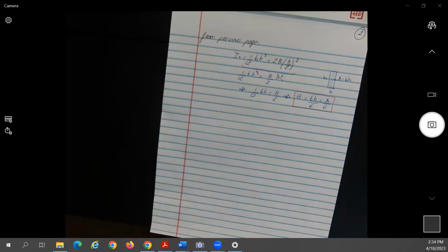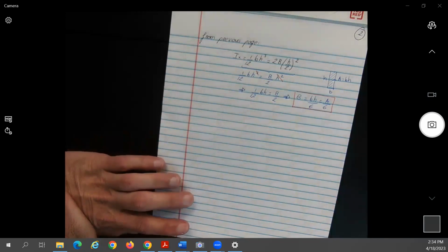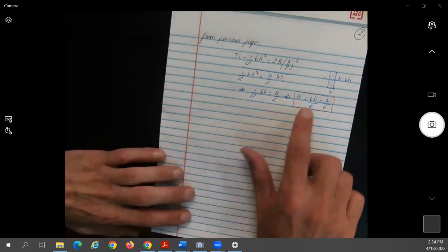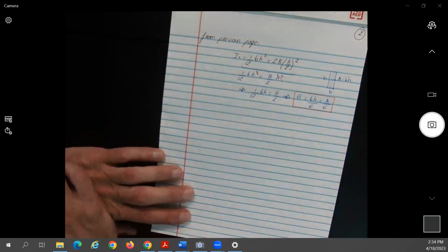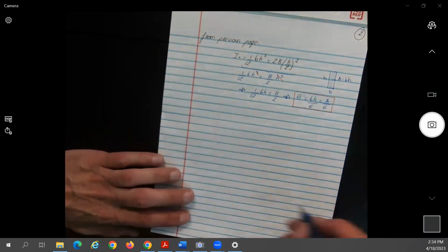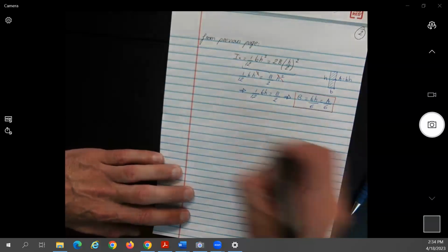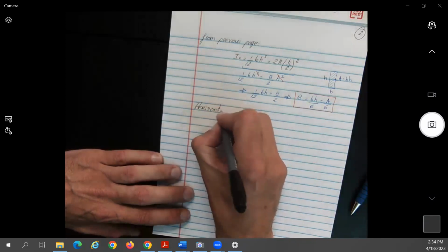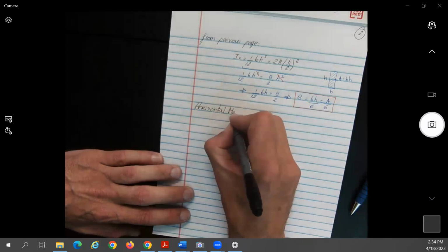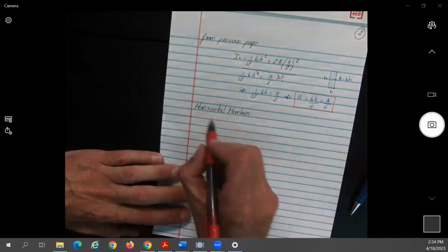So anyway, this will be here for the vertical members. To go from the real structure to the ideal structure, the area of the boom area will be the area of that panel divided by 6. Now we're going to look at the horizontal. So we looked at the vertical, let's look at the horizontal members.